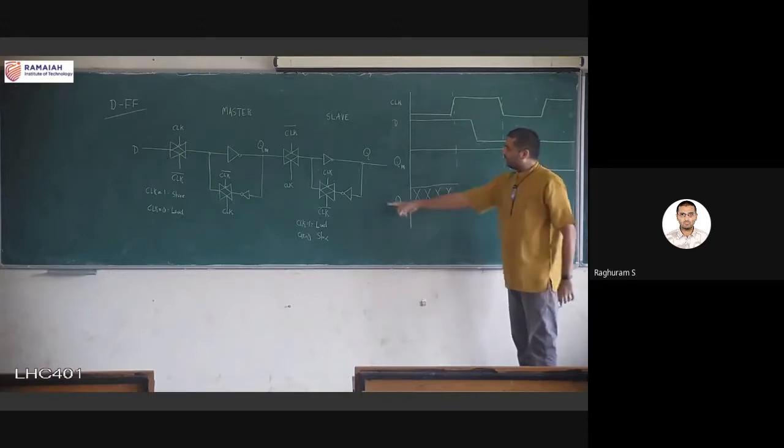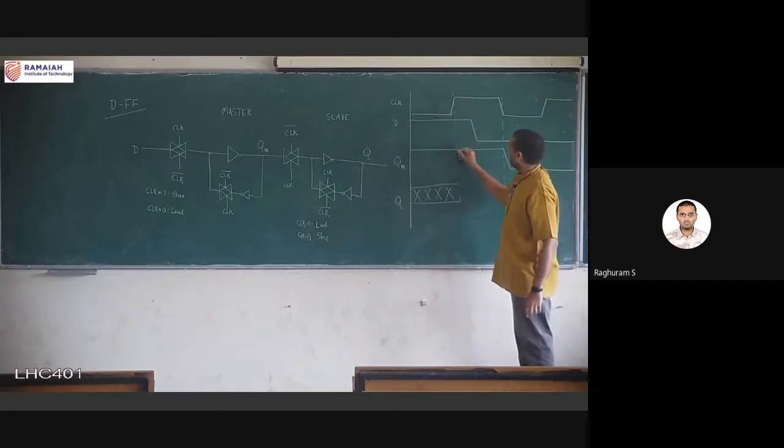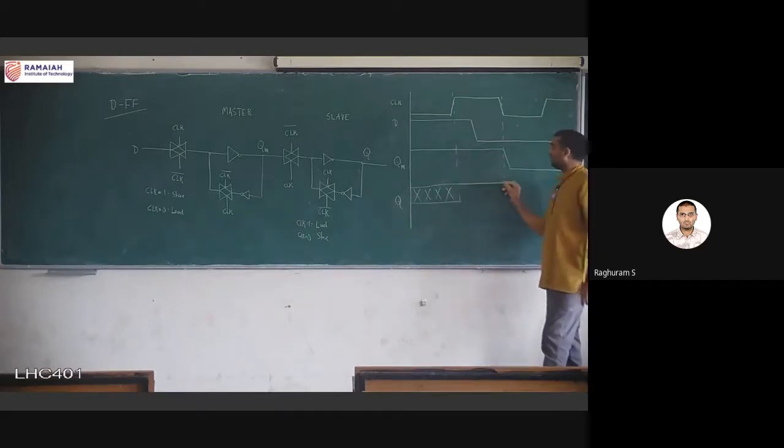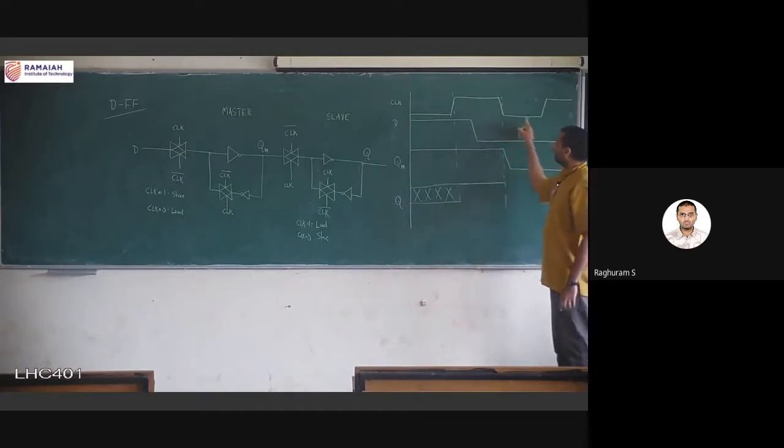So clock equal to 1 is load, and whatever is in QM will come here. QM is not changing, so it stays at a constant value as long as clock equal to 1, and when clock equal to 0 this is just storing.